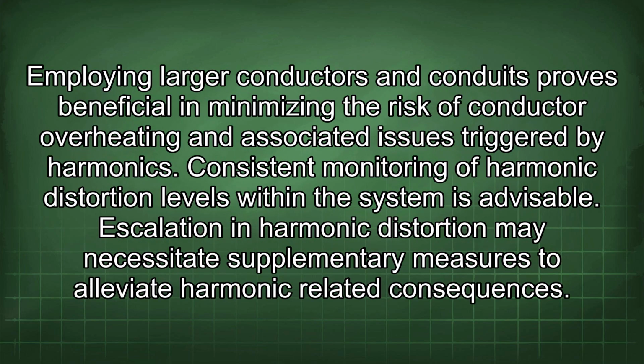Employing larger conductors and conduits proves beneficial in minimizing the risk of conductor overheating and associated issues triggered by harmonics. Consistent monitoring of harmonic distortion levels within the system is advisable. Escalation in harmonic distortion may necessitate supplementary measures to alleviate harmonic-related consequences.